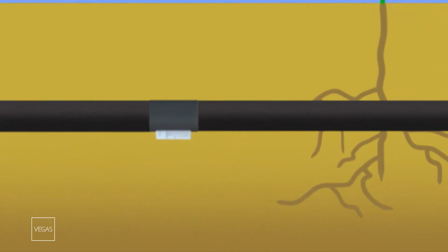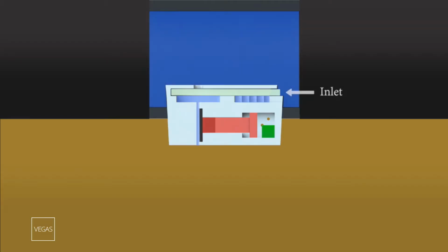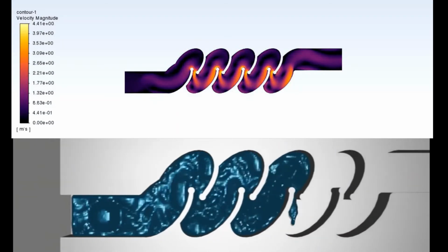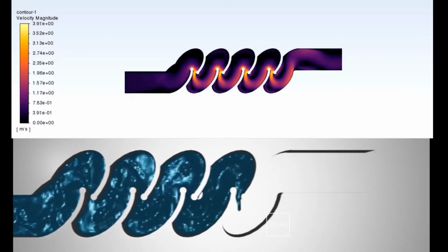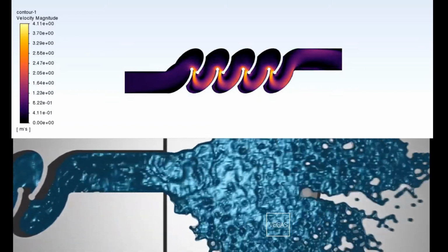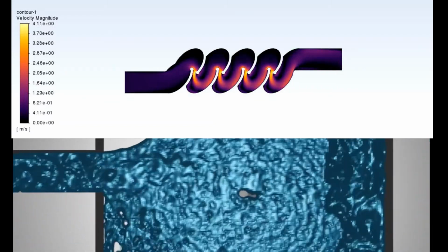Water from the pipe flows into the emitter through the inlet, and the pressure is reduced in the labyrinth before going through the outlet. In order to reduce variation in watering and complexity of drip emitter systems, we developed an optimized labyrinth path using CFD that enhances turbulence, which reduces clogging and produces a more efficient pressure drop, allowing for a bigger and better filtration system within the emitter.